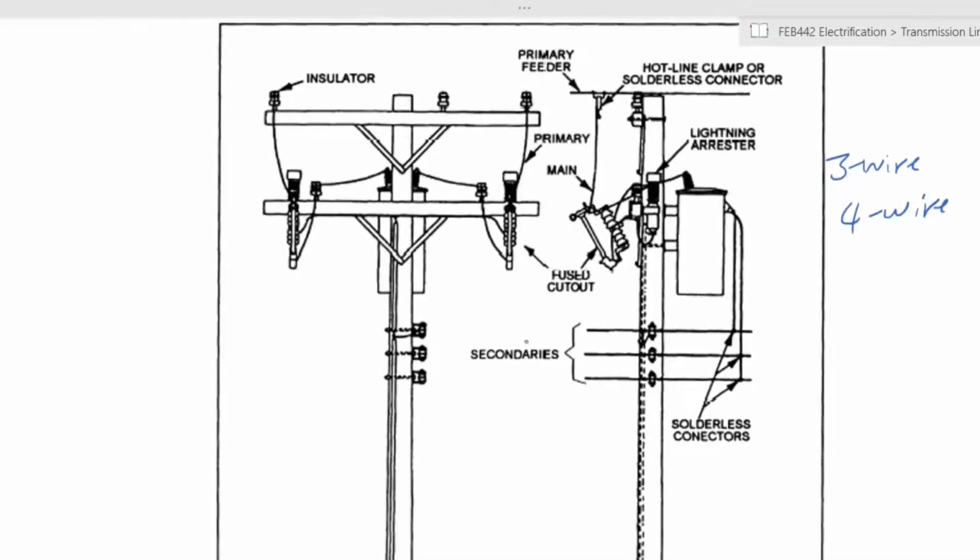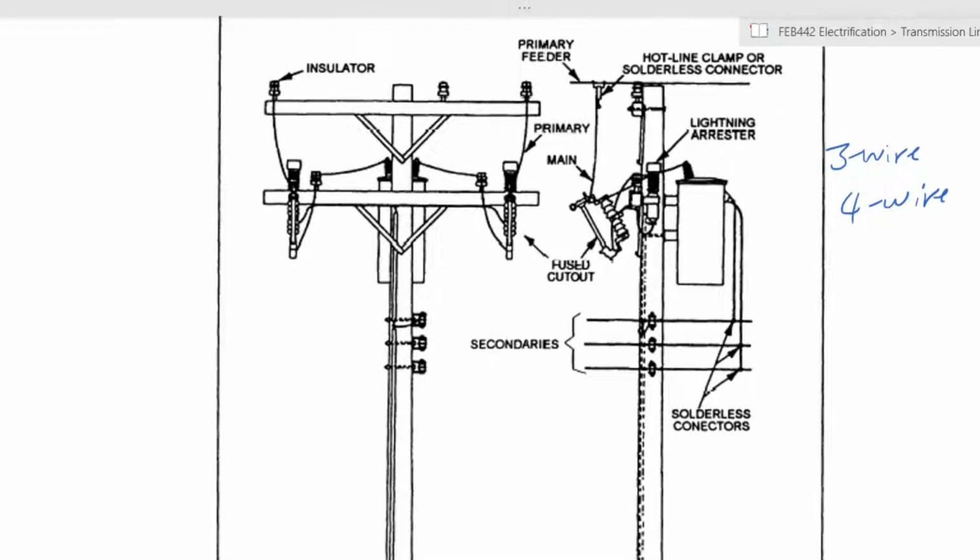So let's look further at the pole mountings of overhead cables. So this is your standard pole. When you walk outside, you will see generally this kind of pole, slightly different configurations from place to place, but the components of the pole themselves usually are the same. We can start from up here. The insulator that you're seeing prevents the cable itself from directly coming into electrical contact with the pole, and that will lead to a short circuit and a fault. So you have to completely isolate it electrically from the pole.